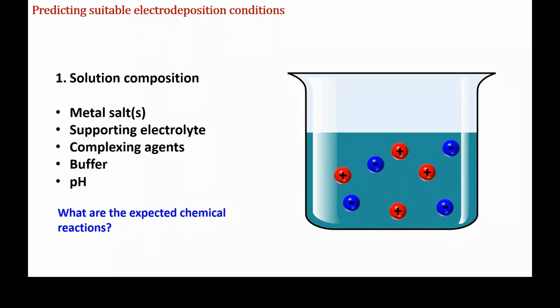So keep an eye on pH, and on something called complexing agents. We're coming across that a lot now in my group, where we're looking again at nickel deposition, trying to get a very smooth nickel deposit. It turns out you need lots of complexing agents, and initially it's not clear why. So I'll show why they are important and how to look at what they're expected to do.